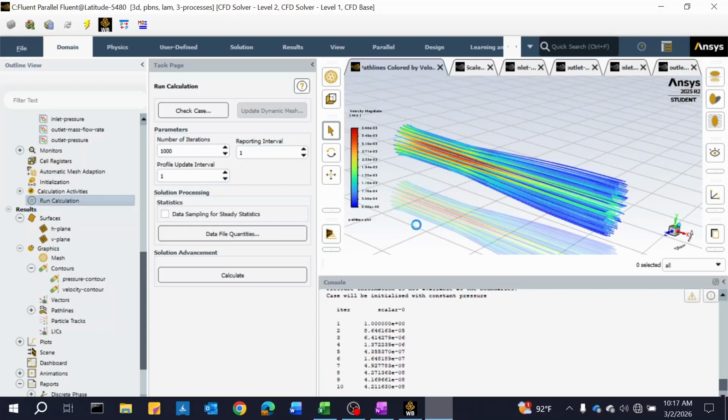So once that is done, you compute your pressures at the inlets and outlets. Mass flow rates at inlets and outlets should be the same. Get your total loss pressure from the named expression, and then get your pressure contour, velocity contour, and path lines. Just save the images, and you populate your table. So I won't be showing all those because of time. I'll be going to turbulent flow, how to set up the system for turbulent flow.